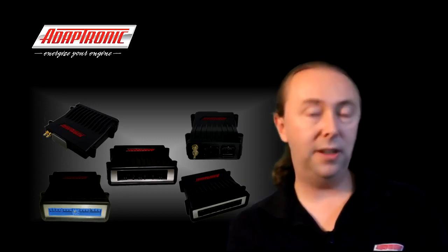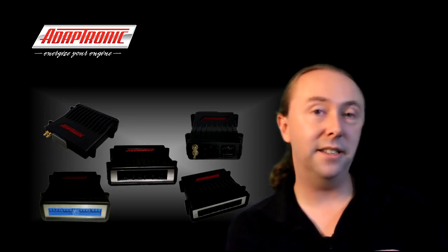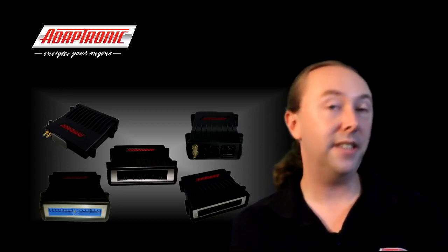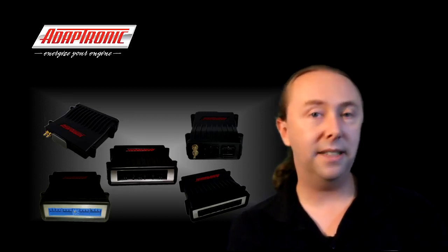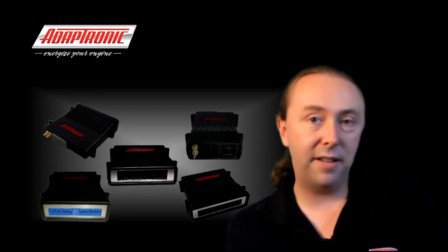Sometimes people do this, or the worst one is when people convert a car to high impedance injectors and don't short out the resistor pack that was in the car originally when it had low impedance injectors, and then they wonder why they don't open at the low voltages. It's because there's just not enough current there to open.